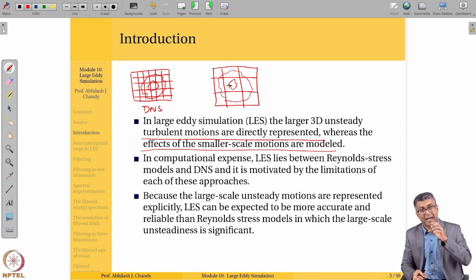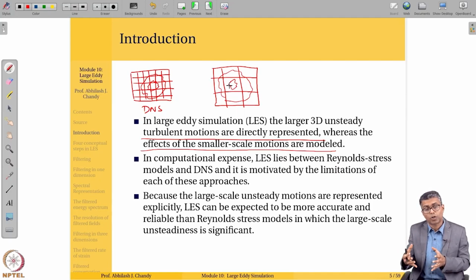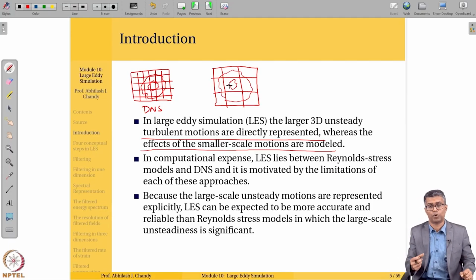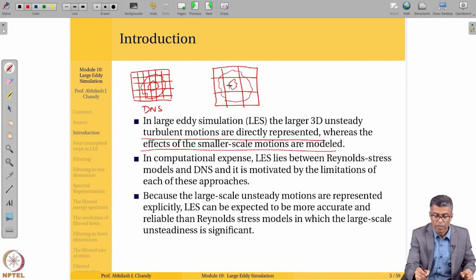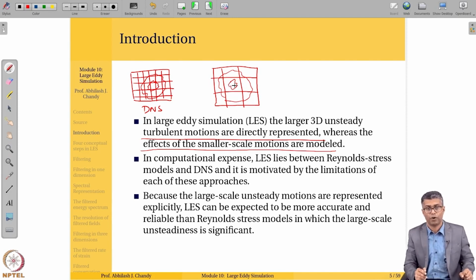Now here, mathematically, the subgrid scale model comes about in an effort to close some unclosed terms that pop up when you filter the Navier-Stokes equations. Let me repeat that. You have the Navier-Stokes equations. When we filter that, there are some additional terms that are going to pop up. Those are the residual terms that account for these small scale motions that I've drawn. And you will need a model for that because your grid is not fine enough to resolve that.